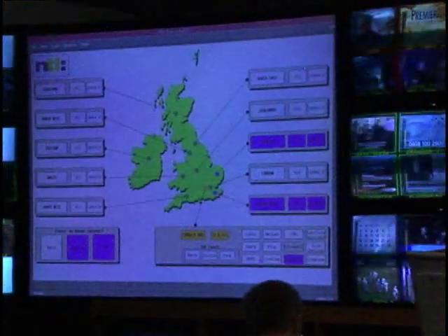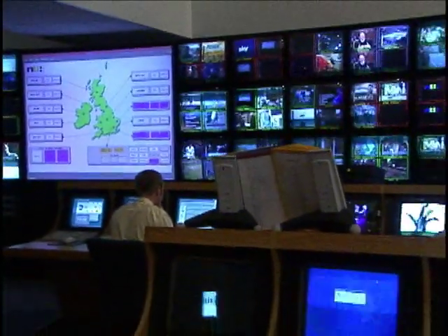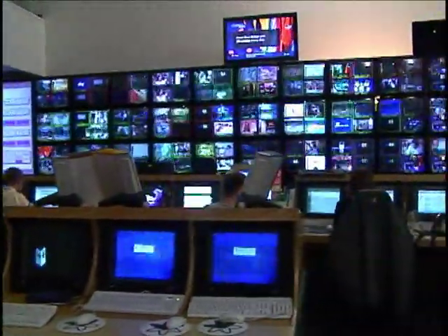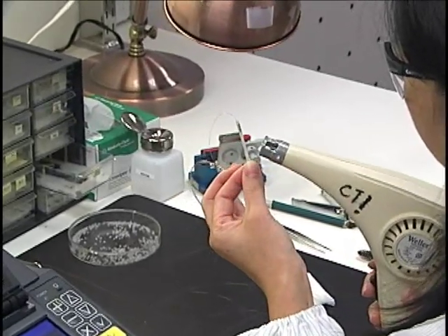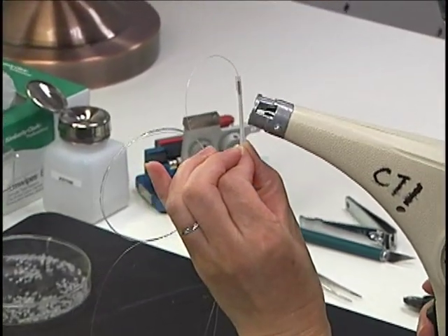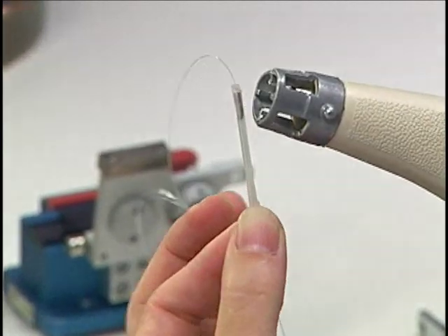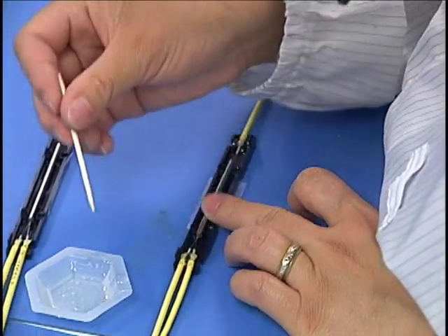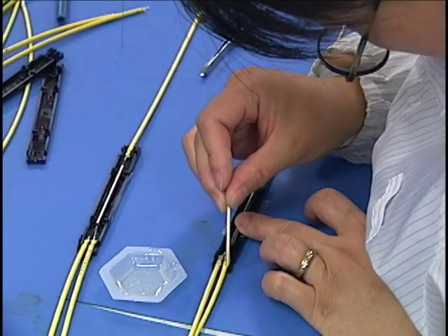In the case of CATV networks, the use of optical splitters allowed for broadcasting of video signals to thousands of subscribers through the hybrid fiber coax systems. Splitters are also known as couplers and have a number of characteristics that determine their function and application. These include the number of input and output ports, signal attenuation, the directionality of the light transmission, wavelength selectivity, single or multimode operation, as well as the polarization sensitivity and the polarization-dependent loss of the device.